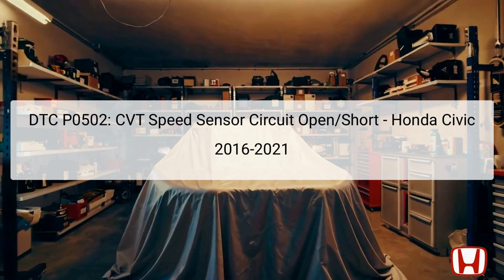This sensor sends a pulsing signal to the transmission control module, TCM, which then converts this signal into vehicle speed information. If there is no signal detected from the sensor for a minimum duration of 4 seconds while the secondary driven gear is rotating, the TCM concludes that there is an issue in the circuit and logs this DTC. A failure in the circuit can stem from multiple issues, including poor connections or direct sensor failures. Indicators such as the malfunction indicator lamp, MIL, illuminating and the shift position indicator blinking will alert the driver to the issue.